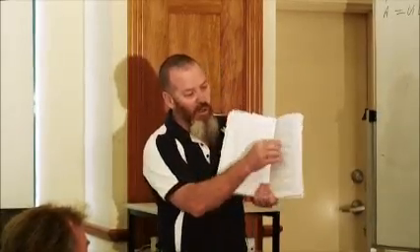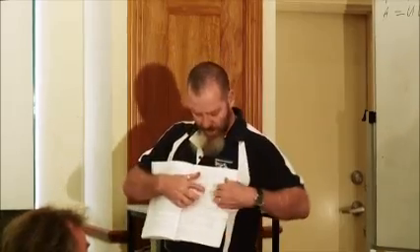And again, you look at the lines above it and what you'll see, that line there that's outlining what the ULW is on that outside wall is halfway between where the rafter is connected at the top plate and where the rafter is connected at the underpurlin. So again, the formula's there. Half the distance between connections plus the overhang.